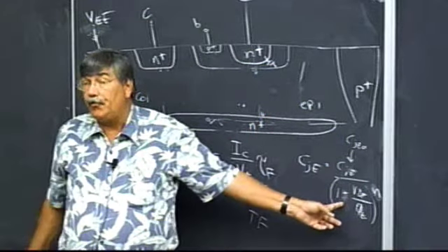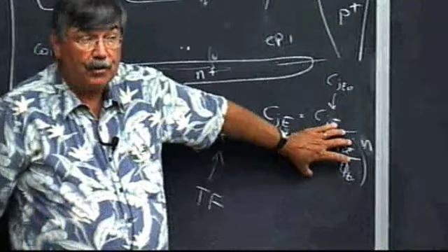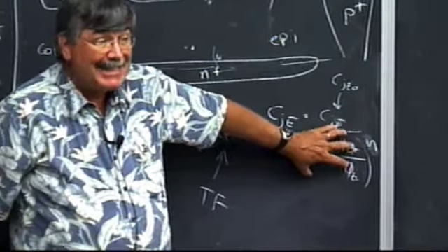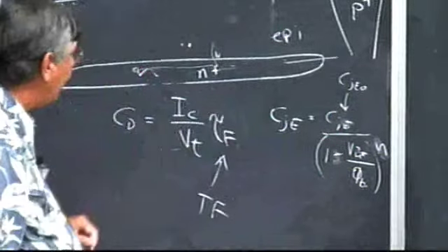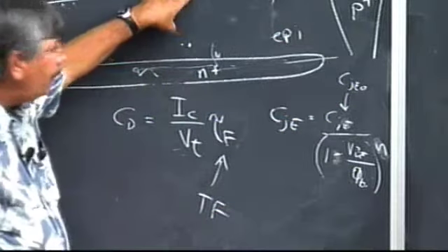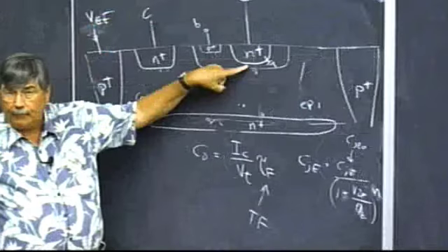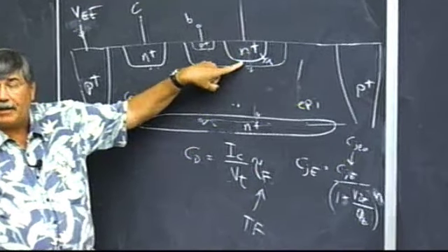This is the one that's usually forward biased, so usually you don't use this for hand calculations. We usually replace this by 2 times CJE0. Anyway, you've probably forgotten that, but that's what's going to happen there. This one is a pretty large capacitance per unit area because this is a fairly high doping. The high doping also means that it's got a fairly low breakdown voltage.